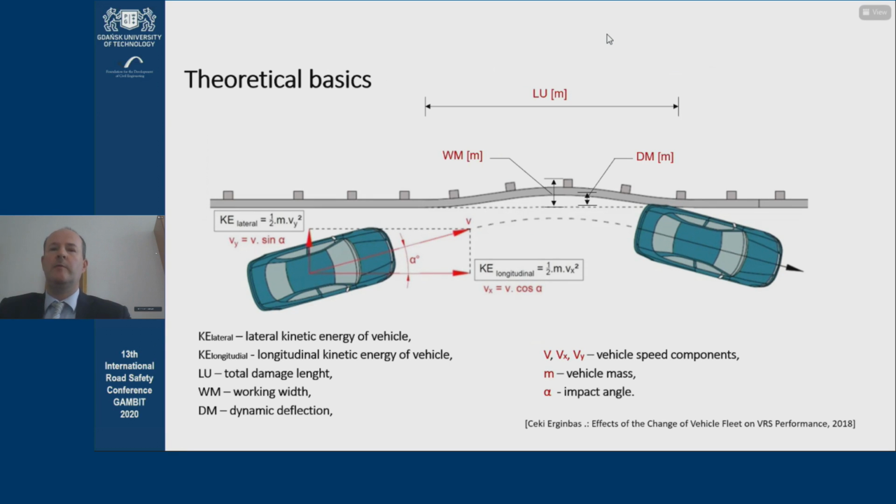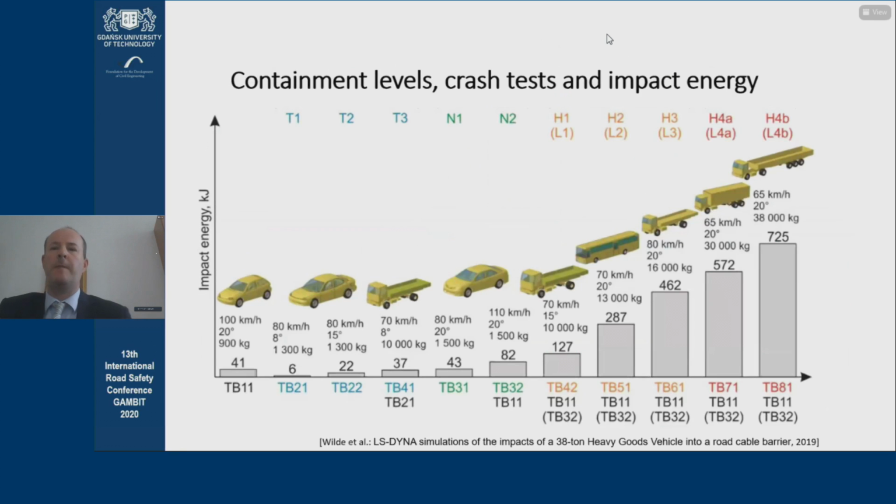Also, it should not impact the environment in a negative way. When we look at the theoretical basis for the functioning of the barriers, when there is impact, there's a crash, it all is based on the kinetic energy at impact. So, the kinetic energy will obviously depend on the mass, the weight of the vehicle, the angle of impact, and the velocity.